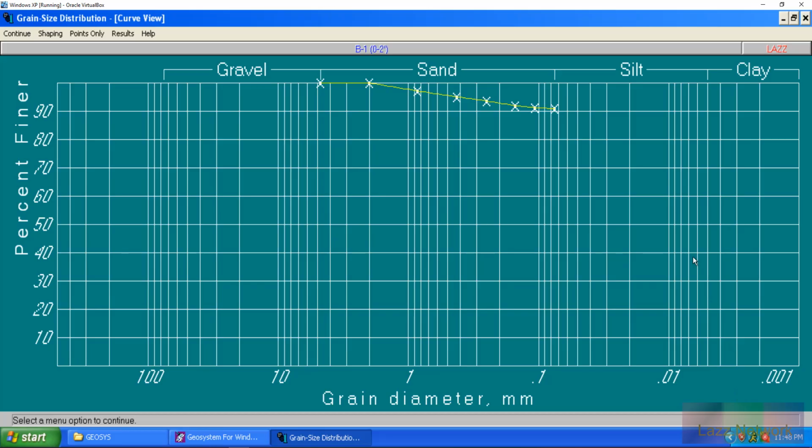I like to emphasize this point for any lab person that might come across this. Remember, guys, if there's no tick mark in between your readings, so if you're between 4 and 5, you can't say 4.5 unless there's an actual tick mark that indicates your half mark. And I get it. The accuracy would be, well, it was in between those two, but was it actually 4.5 or not? There's no tick mark to determine that. And the manufacturer makes it that way. So stop doing that. That's not accurate.